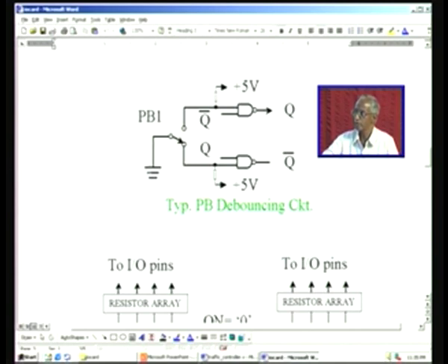And now let us see what happens when you press the push button. So this connection is broken, so it is going to travel all the way and strike at this point. Before that, let us have a look at what happens. Because the connection is broken here, this one which was forced to 0 will be 1, and because this is not yet connected to this ground, that is also 1. So 1 1 would mean a store mode in an SR flip flop, and that is precisely what we are exploiting here. And remember, it was 0 and 1, so this 1 was fed here, and 1 into this is still 1. 1 into 1 is naturally 0. So that is how the store mode is working.